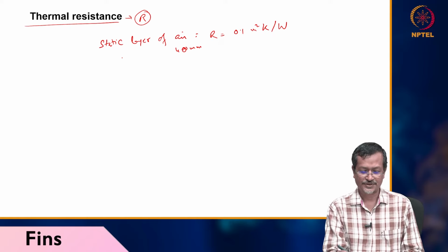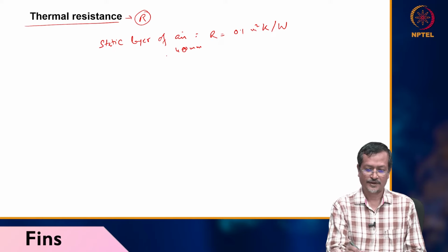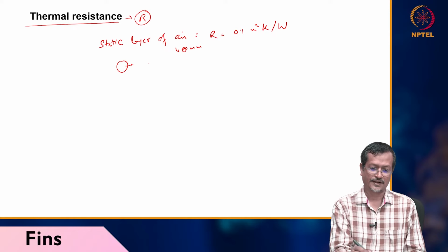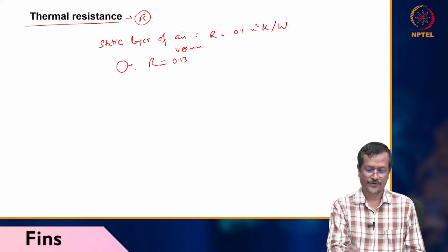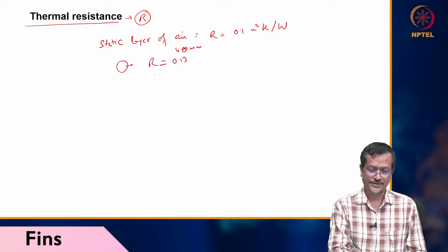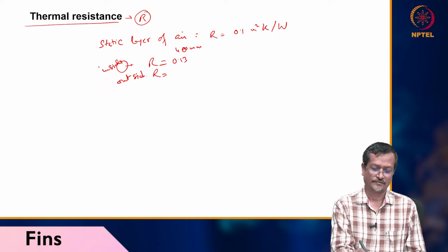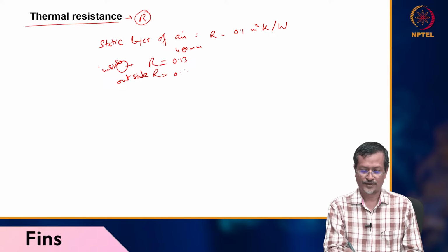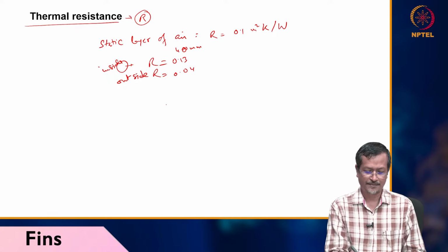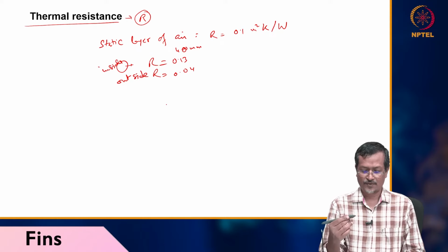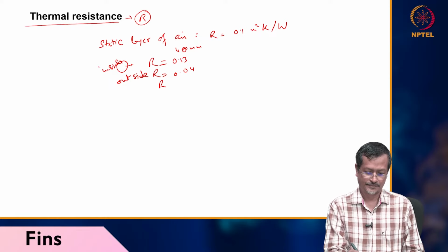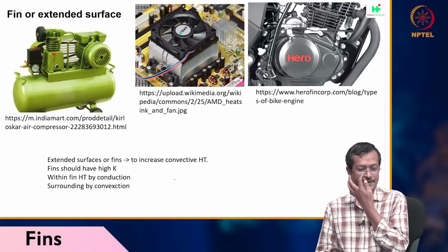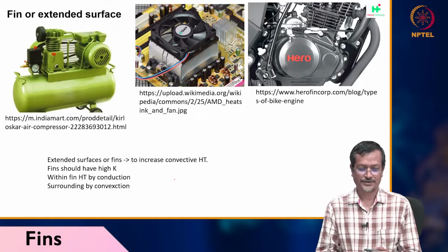Inside pipe heat resistance with horizontal flow, R will be 0.13 for air. Outside resistance will be 0.04, same units. Inside heat transfer resistance with heat current from down to upward, okay, leave it.